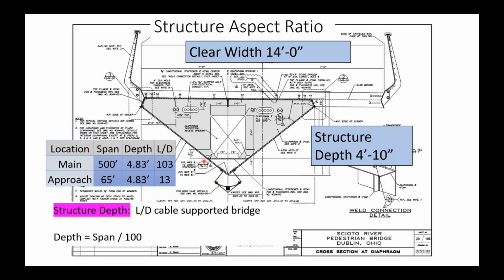We did introduce a bottom flange kind of hidden inside the box to carry some of the tension and compression in the positive and negative moment regions. So we really kind of ignored the bottom triangle in our design. We definitely had to look at it to see that it wasn't overstressed, but the primary structural flange was hidden inside the box, and it created kind of the traditional bottom flange. A rectangular shape certainly would have been more structurally efficient, but didn't have the aesthetic benefits.